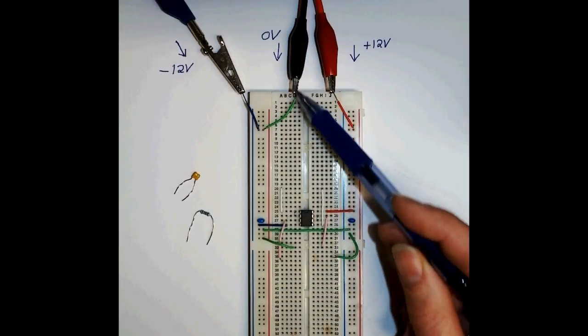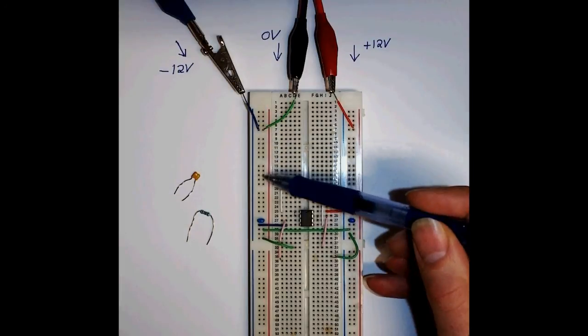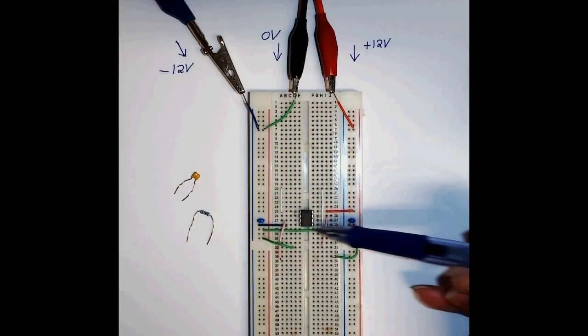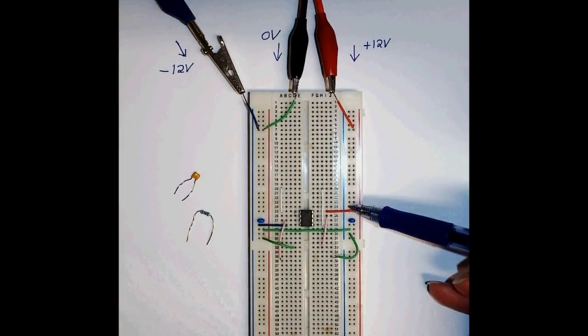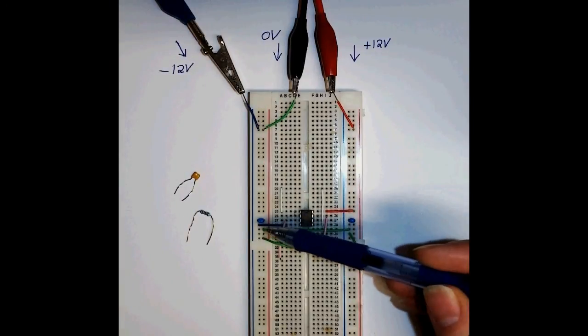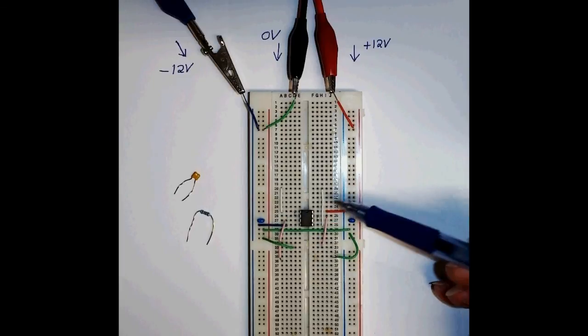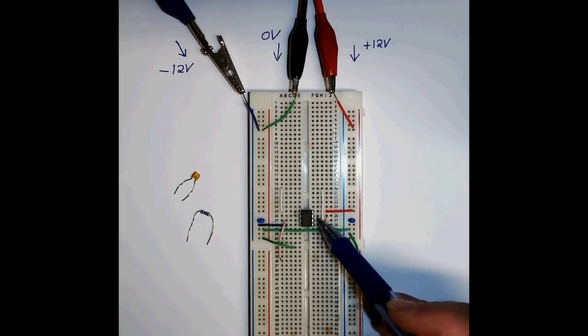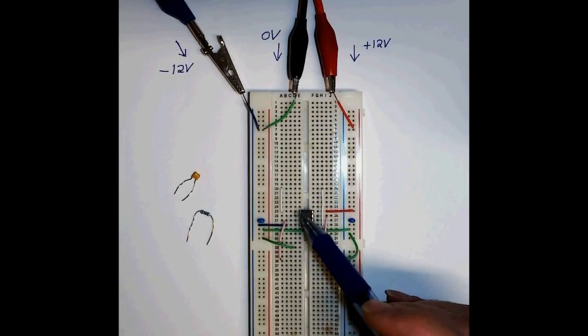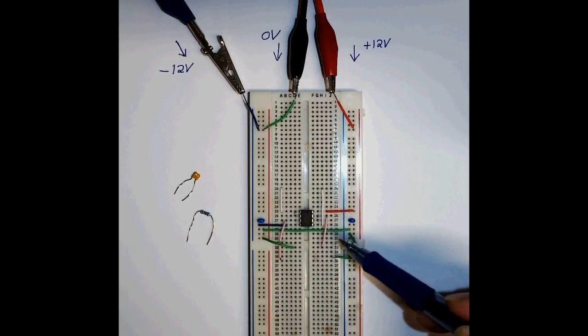The 0 volts from my power supply is connecting to this rail on the breadboard, and across this long green wire here to this rail on the breadboard. I've color-coded the wires because that makes it easier to see what's going on and debug. You may not be able to see them, but I've put some tiny little wire links in between pins 7 and 6 and pins 1 and 2. That's the feedback from the output to the inverting input of the op-amps.